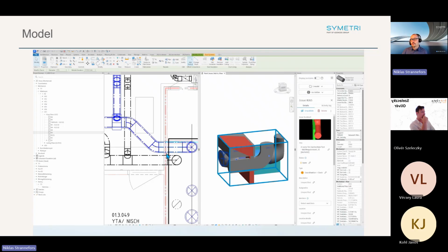Oversimplified, that is a text file or HTML file with two coordinates: where the camera should be and where the camera is looking. You get a photo, and some connection to it if it's hosted on something like BIMcollab or a third-party site. You can connect that to an issue, you get some information, and you go through them one by one. It works, quote unquote, the same. The only difference is you need to create this BCF format, like an open format. But otherwise, it looks the same. But ACC, Autodesk Construction Cloud, has all this built in.